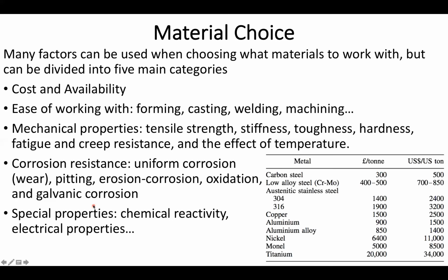And again, the last major feature we need to watch out for is going to be things like electrical properties, because it turns out that we don't always want our pipes to be able to conduct electricity, especially because there may be things like static buildup as I'm sending lots of fine materials like sand or catalyst particles across a surface.